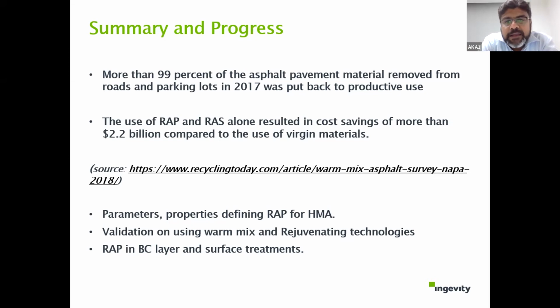And one of the areas where we recently, in the last 2 years, saw something interesting is RAP being used in cold mixes. Like you take the finer part of the RAP. Once you start generating more RAP, you segregate it and do all the fractionations, and many times one fraction is not used and the remaining fractions are used. So what do we do with that?